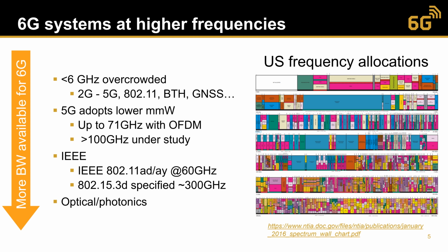Current telecommunication networks have been deployed mainly below 6 GHz, but those frequencies are practically congested. The highest 5G data rates are available at millimeter wave frequencies, but deployment of such networks has been slower than earlier anticipated. The Wi-Fi system has traditionally used 2.4 GHz and 5 GHz frequency bands, and then there are two higher frequency options for Wi-Fi as well. The first one uses the 60 GHz frequency band, and the second one can be deployed from 250 GHz up to 320 GHz.